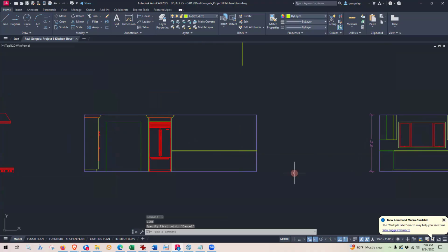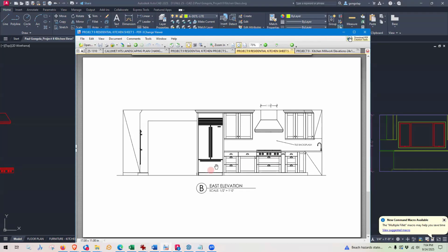Let's draw our floor base. Actually, you know what? Before I draw my floor base, I want to draw the side of this counter. This counter is an L shape, if you remember. We've got this, and then it comes out this way. We've got our sink over here. And these lines, by the way, indicate a section or cut through the millwork. You can or not show it. I generally don't like to show it, just because it looks nicer without it. But technically, if we were doing technical drawings, we would show those diagonals.